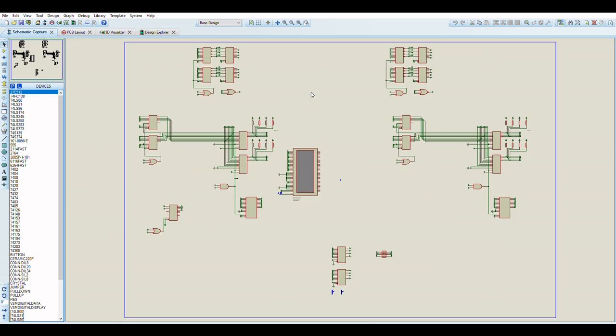The Sprite scanline logic is perhaps the most interesting part of the entire schematic, because it uses the entire 384 clocks of the horizontal pixel clock, of which 256 are visible, to calculate and write all of the potential maximum pixels for 24 sprites of 16 pixels wide.